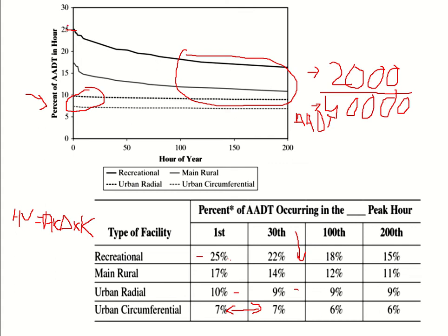And you cannot take the highest as well. As I said, it will be overestimating. You are increasing your value by 400-500 vehicles just to incorporate an extra 20-30 hours. So it doesn't make any sense. So we try to be close to this portion of the year, the portion which is almost straight. So we try to ignore most of the part of the peak, not most of the part of the curve.